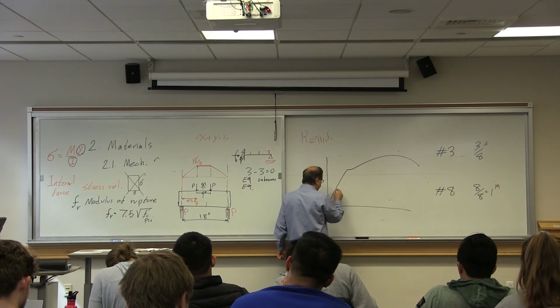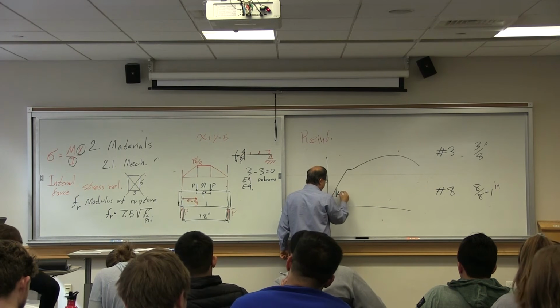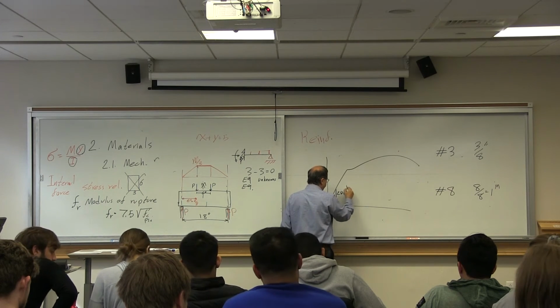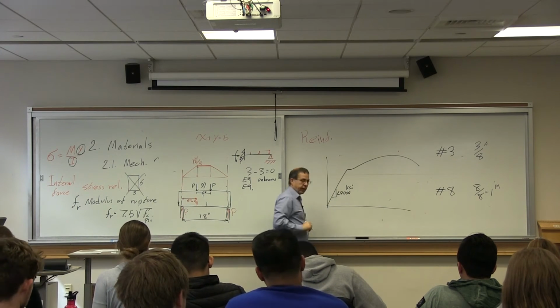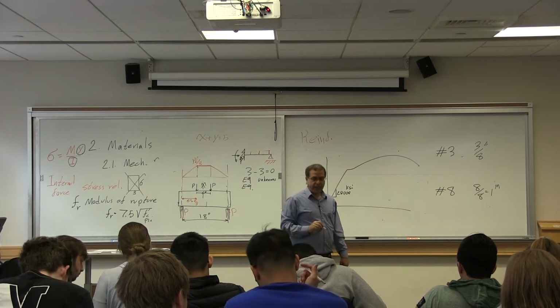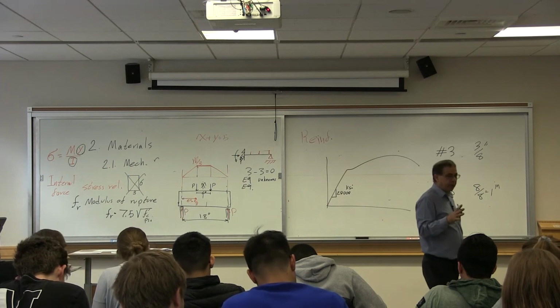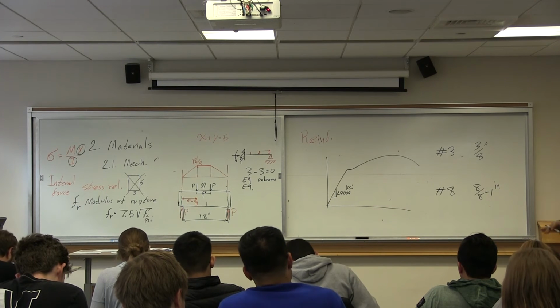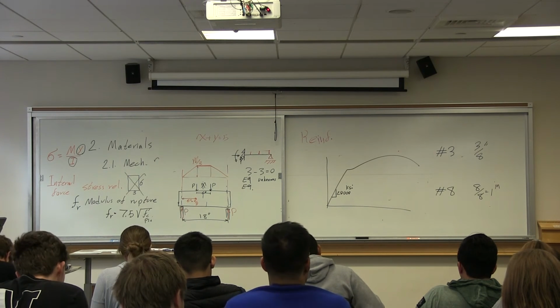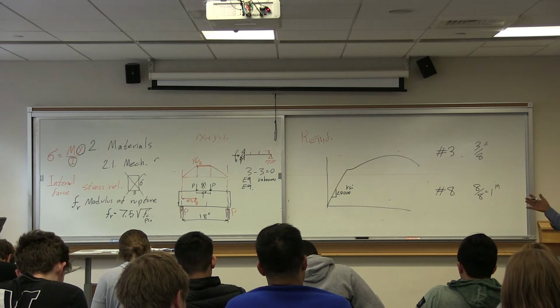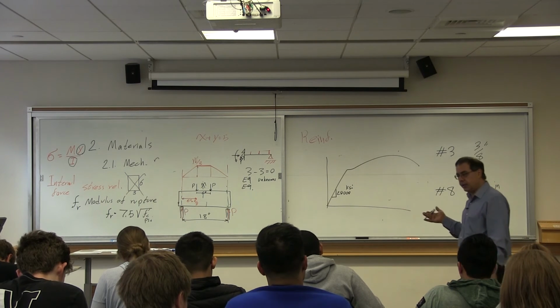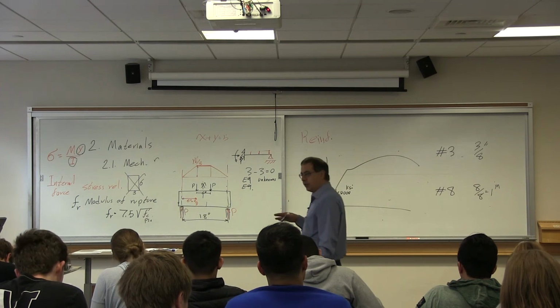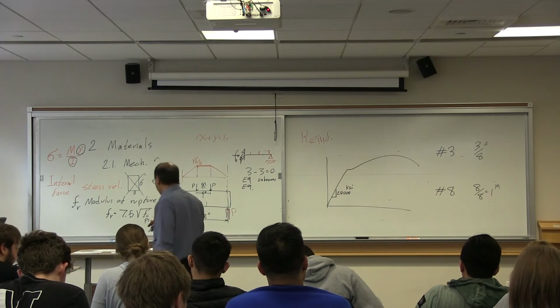The modulus of elasticity is approximately 29,000 ksi and is constant, unlike concrete, regardless of the strength of the rebar. If the strength is 40 ksi, 60 ksi, or any other number, the modulus of elasticity of rebars does not change.